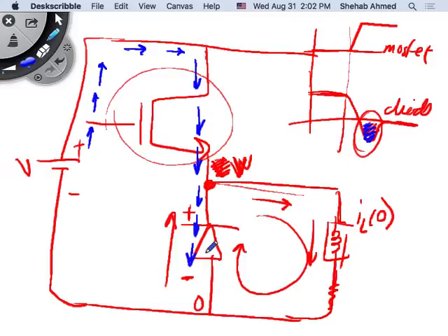in this diode, right? Current was flowing this way in the diode. But in a dynamic state, during a very short transient amount of time, because the diode is not blocking yet, what happened is I turned on the MOSFET, and this reverse current coming from turning on the MOSFET is now being split up between trying to put the diode in reverse mode so that it starts to block, and of course feeding the load because it's a parallel impedance.